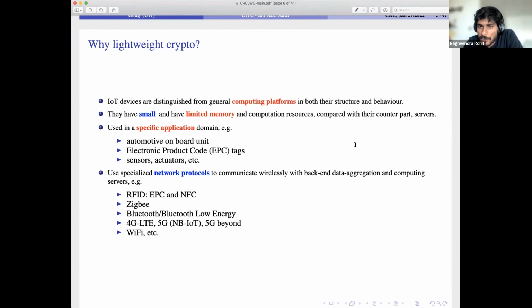I don't see any other questions from the audience, but I still have another question for you. Considering the physical layer, what could be the constraints in terms of lightweight ciphers? Yes, I believe the message format is one of the constraints, because currently the physical layer modulation is OFDM, orthogonal frequency division multiplexing. They have a format where each message block is 96 bytes.